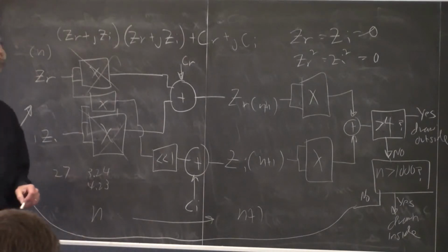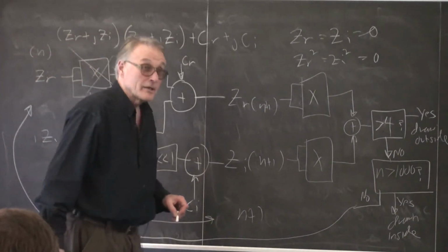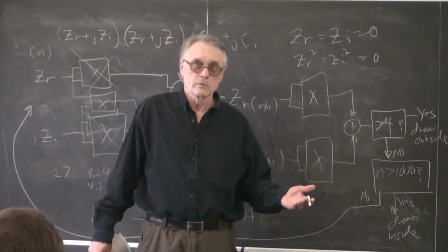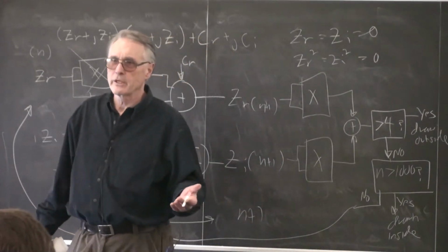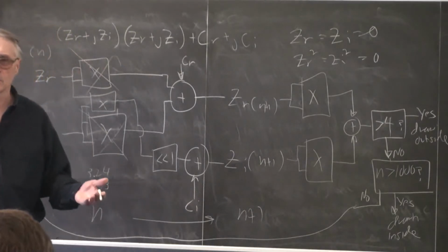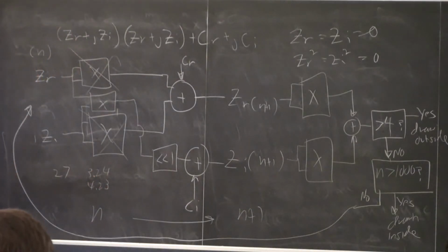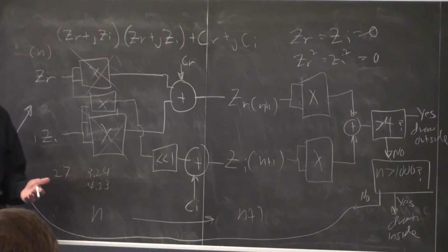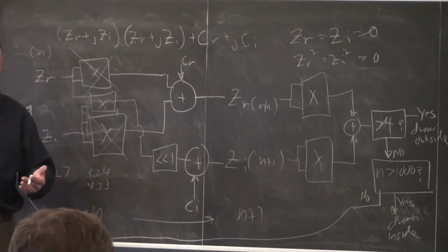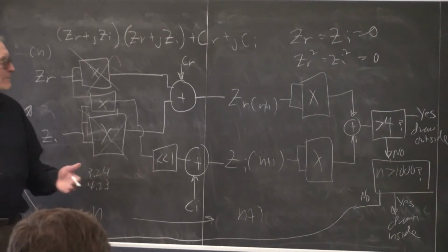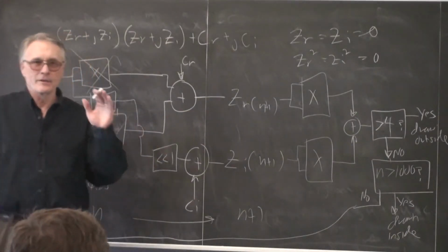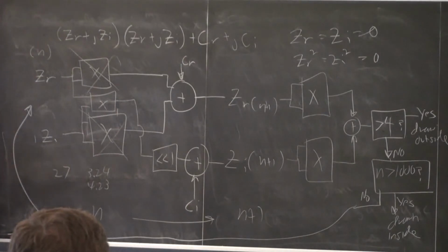So if you used 3 per pipe, you could still do, what, 27, 28 pipes. That's a lot. So maybe that's not a rate limiting resource. Maybe what you do instead is you parallelize it by saying we're going to do all 3 multiplies at the same time, and try and get the whole result, one iteration done in 1 cycle or maybe 2 cycles.